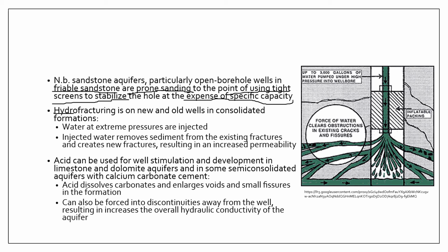Now, another method for well development is hydrofracturing, and this can be used in new and old wells in consolidated formations. So, typically, your rock formations. And hydrofracturing involves extreme pressures, and of course, extreme pressures loosen up all your fractures, as well as they can also induce fracturing within the formation for increased permeability.